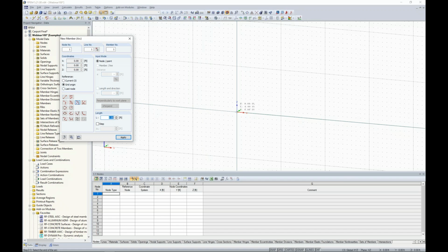So I snap to the origin at 0, 0, 0, and then my second point can either be defined on my work plane here, but in my particular case, I don't have exactly 1 foot increments for my second point, which is what the default is for my drawing grid. So what I can do is just type in the coordinate points directly at 4.42, 0, and 11. Now you want to make sure not to drag your mouse outside this dialog box because, as you'll see, everything resets to the current position of my mouse on the work plane. So we'll retype that in at 4.42, 0, and 11. We scroll down here to apply.